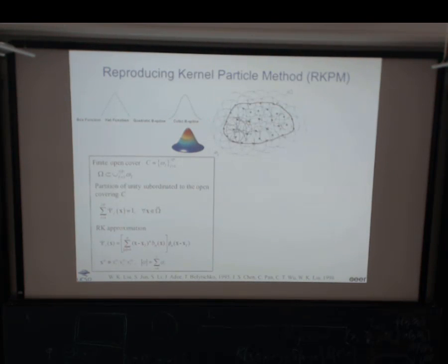This comes free, unlike FEM, as you know, because they have to be conforming. Therefore, continuity has to be imposed along the element boundary. And just to get C1 in 1D, you have to use up to third order polynomial because you have to have more terms to make sure the derivative is continuous. So every time you increase one order of continuity in FEM, you pay for it by increasing the order of polynomials. But here, you don't have to. These two are entirely independent.